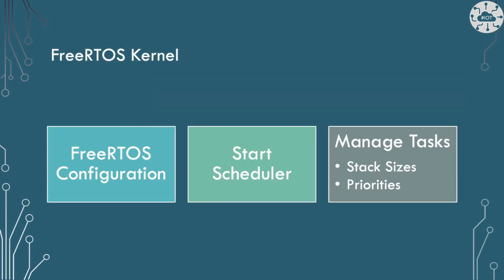Yes, there's a little more we need to worry about with FreeRTOS. The library needs some configuration and we need to start the scheduler. Actually, those become largely boilerplate across projects. We do need to think a little about our tasks. We need to give them some memory to work in as a private stack, so we have to define that size. There are techniques for guessing that and then diagnostics to test.